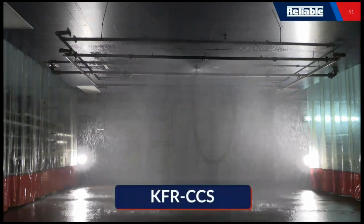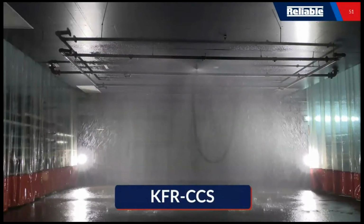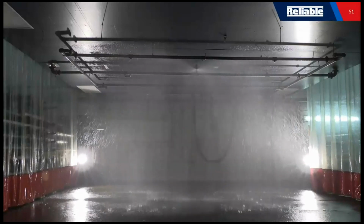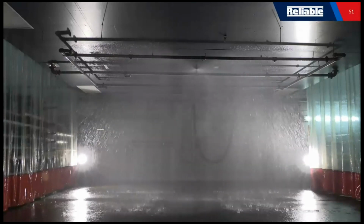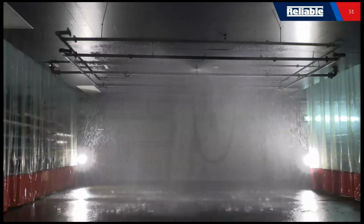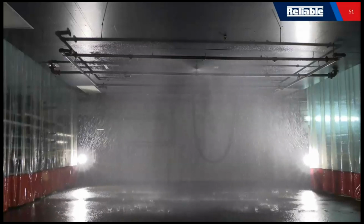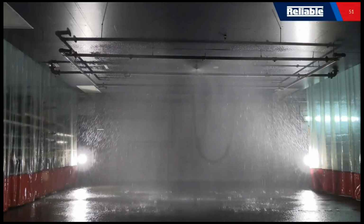The focus of the sprinkler is really the neat spray pattern. It's really flat. We're not concerned about creating that umbrella shape again, because this is in between floor spaces that are very, very shallow. So it's important to get that flat spray pattern and project it out, especially when we want to get up to 16 by 16 feet of coverage area.